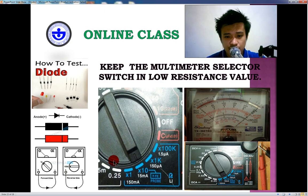This is our illustration. Keep your multimeter selector switch on low resistance. As I said, I suggest connecting it to times 10. But before you proceed to the next step, make sure you set your needle pointer exactly on 0 ohm. Upon selecting this on your selector, you intersect the two test probes as you can see in this picture.